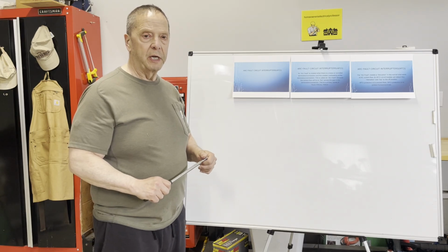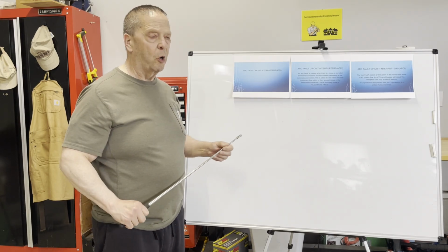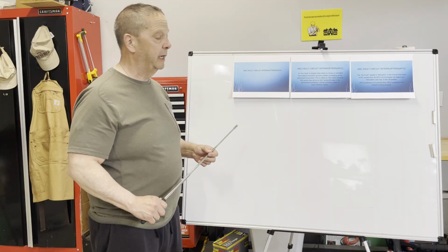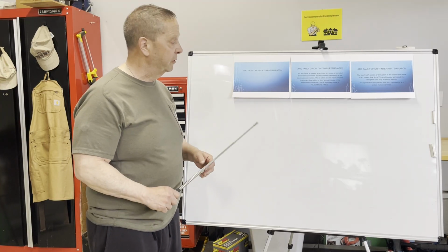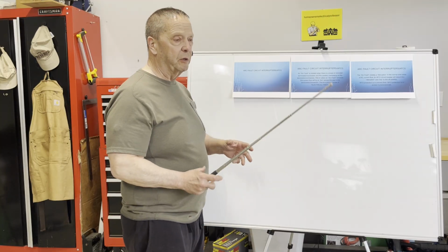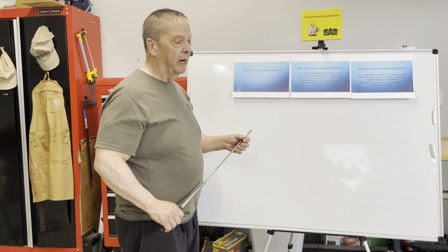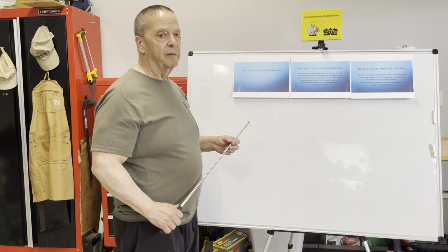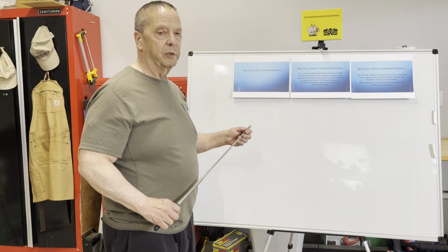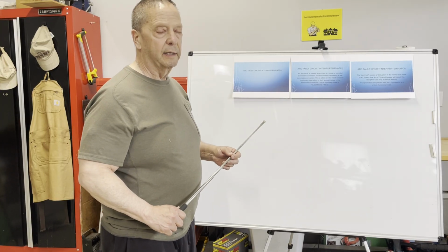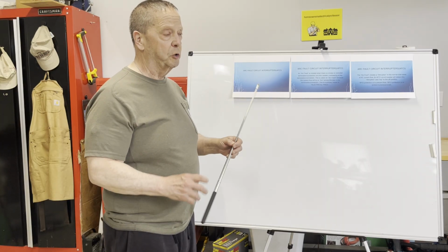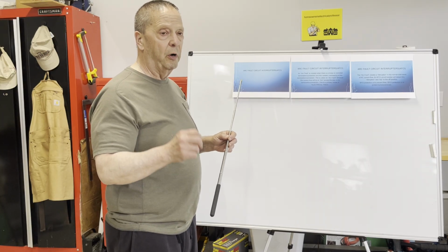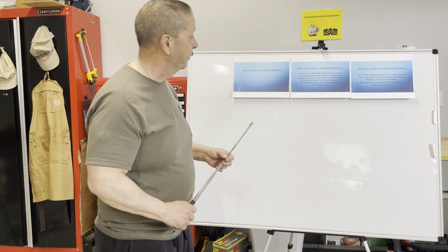Okay, homeowners and future electricians, a little talk about arc faults. The arc fault circuit interrupter can be a circuit breaker. Basically, they do make them in a receptacle variety. I don't think in 20-some years I've ever seen one installed. It's normally just an arc fault circuit breaker, usually a lot of times now in conjunction with a combination arc fault and ground fault circuit breaker.